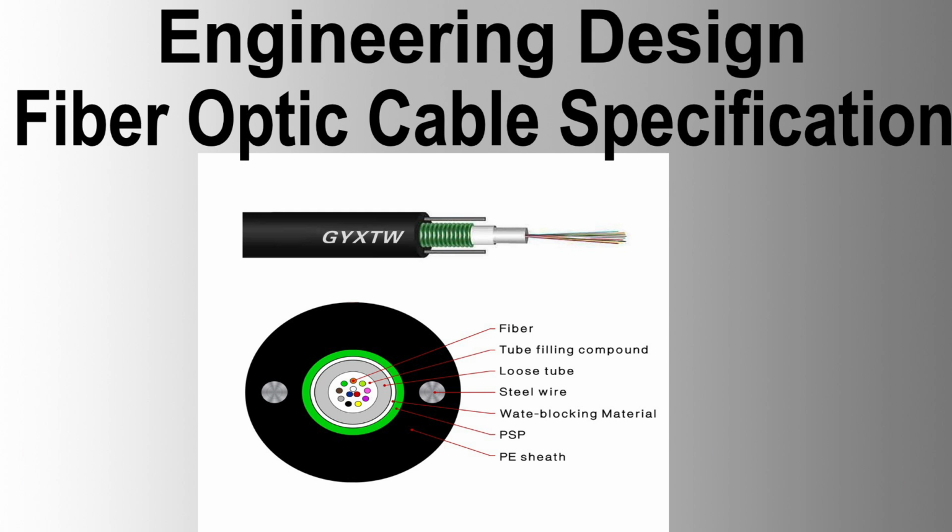Testing and personnel. Test all splices for mechanical integrity and optical performance, ensuring each splice has less than 0.1 dB of insertion loss. Perform end-to-end OTDR tests to confirm splice loss. Only trained, authorized personnel should perform splicing.